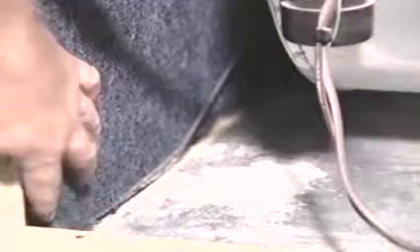The air coming out of the supply register feels somewhat cool and the flow seems adequate, but the air in the house feels humid. Next, go to the basement and check the air filter. It's clean. However, the suction line is warm and the liquid line is hotter than normal.